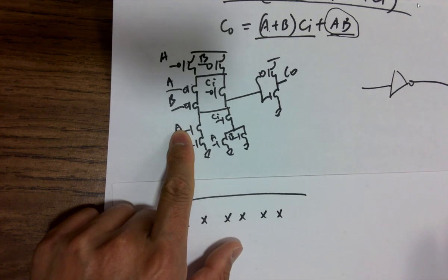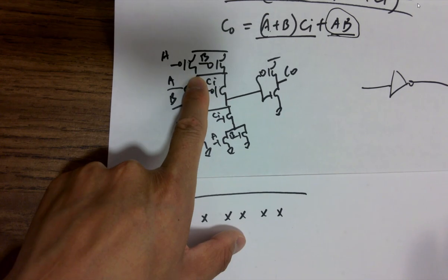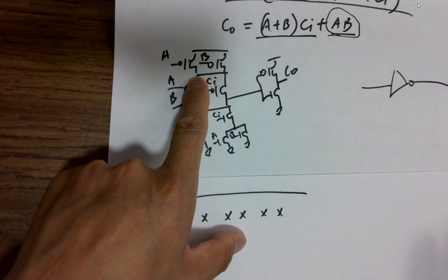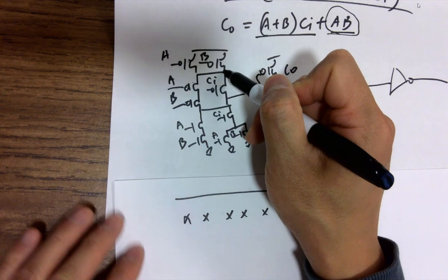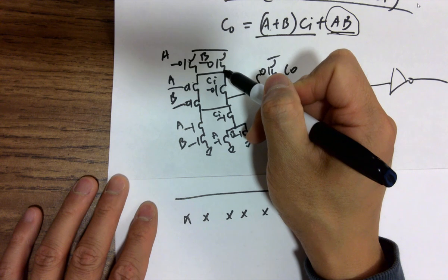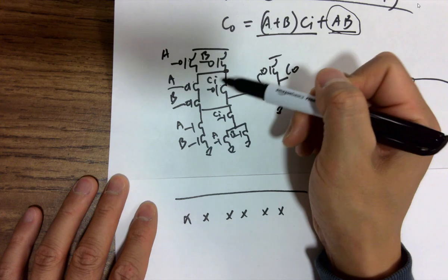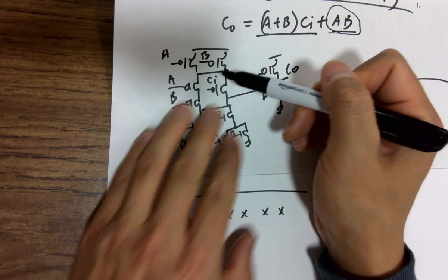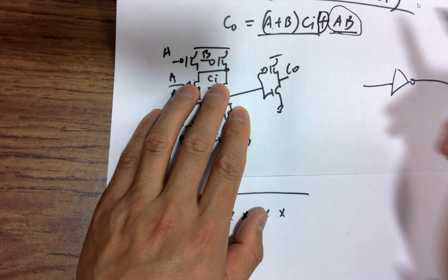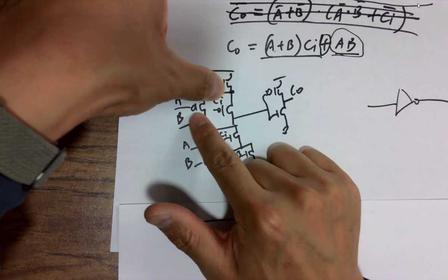The node above the A there, should that not be connected to VDD? Because it's A or B and C in parallel with A and B. Wait, no, it's the NOR logic here. That's the NOR here, right? So these two blocks should be in series on the top, according to the NOR gates.